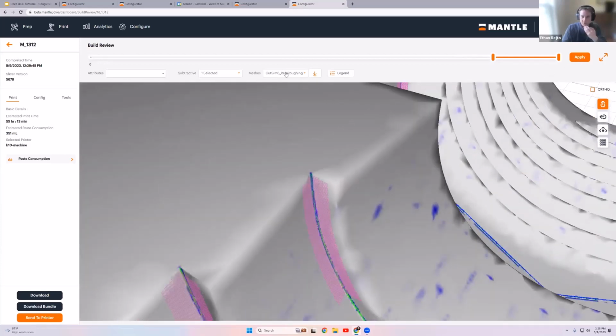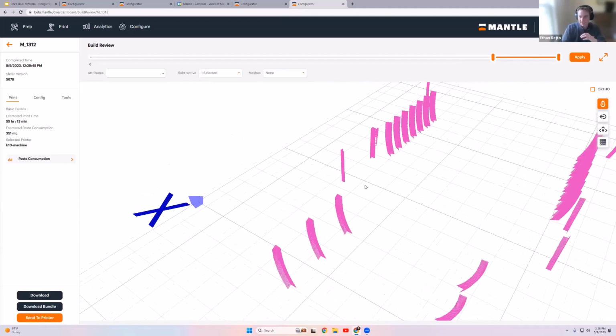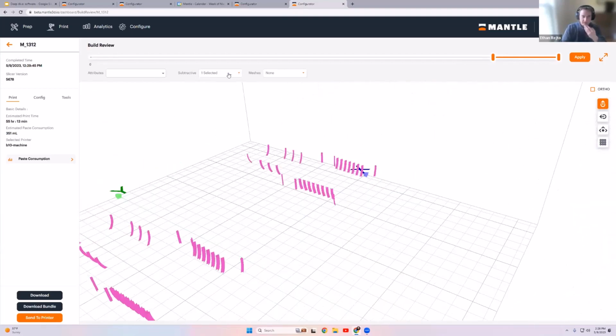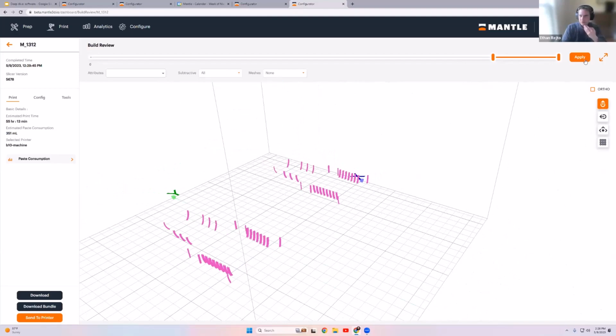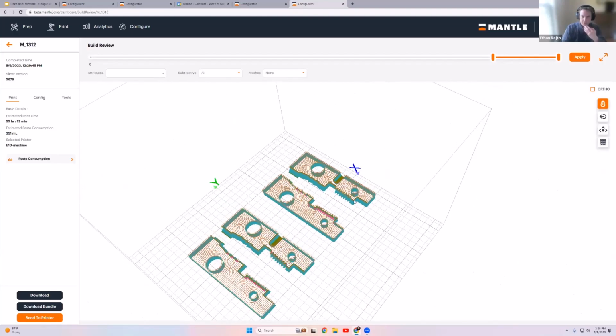Yes, you can see those. Let me turn this off. Those are the tool paths in those sharp regions, just for that 6 thou ball end mill. So you can see this is essentially showing all those parts of the part that have those very, very rough settings. I can turn all these on just to show you all the different tool paths that are going to be involved here to do this.